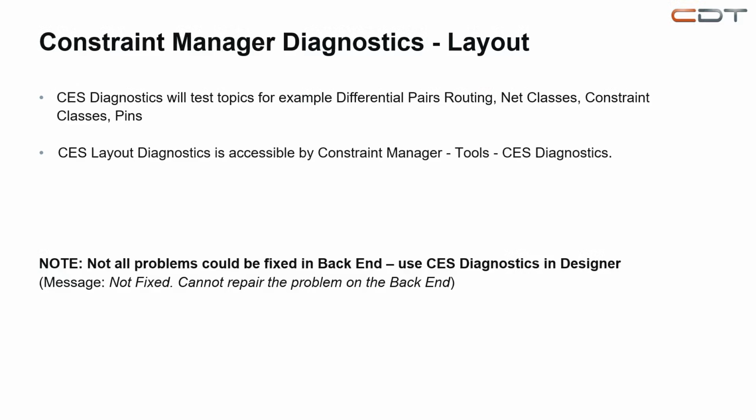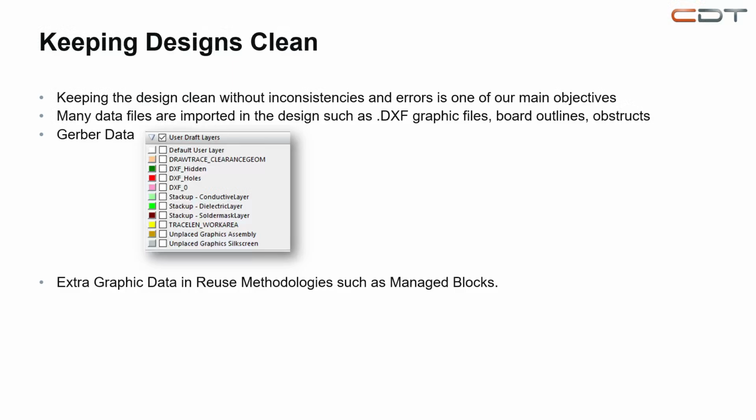In Constraint Manager you go to Tools, then Diagnostics, and as I said, not all problems can be fixed in the backend. Use the Diagnostics in Designer to understand this. It will show you a short message that the problem is not fixed, it cannot repair the problem on the backend. How to keep your designs clean.